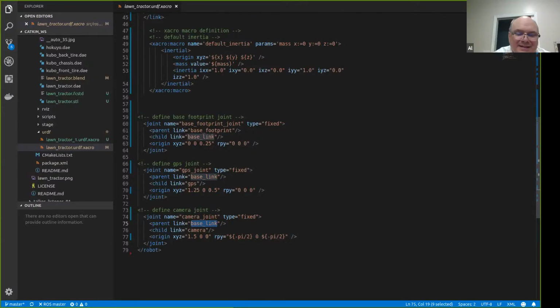And let's talk about orientation. So you've got negative pi divided by 2, so it's a 90-degree rotation. Yeah, negative 90, so counterclockwise and then clockwise. RPY is basically the right-hand rule. Whatever the right-hand rule says, you go around the x-axis. I believe that if my Z is up,